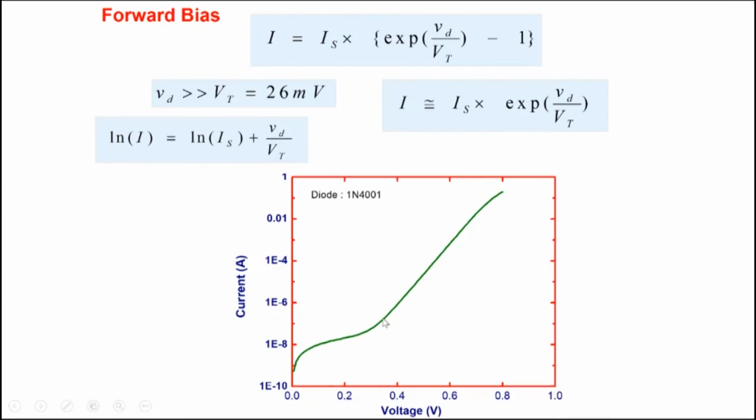What do lower voltages mean? In this case, you can see maybe less than 0.3 volt or so. What does higher mean? Maybe more than 0.8 volt or so. So lower and higher depend on the kind of diode we're talking about. For silicon diodes, maybe greater than 0.8 or so, it's no longer exponential. Because there are all kinds of different diodes, quoting a single number is problematic. But you can see here less than 0.3 or so.